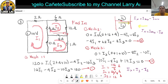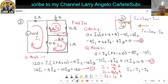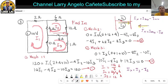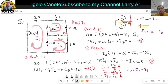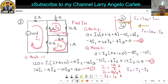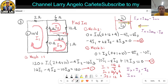If the assumption is to the right, down minus up. If the assumption is to the left, up minus down. Anyway, once you have negative values, it is an indication that your assumption is wrong. It should be on the other side. So we will check muna if the value is positive.